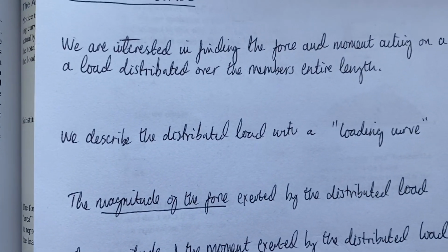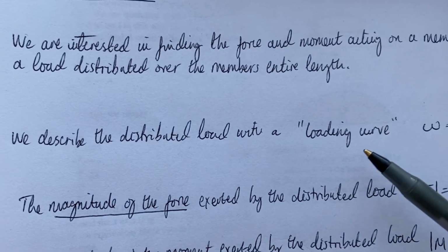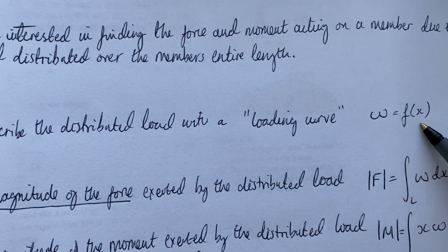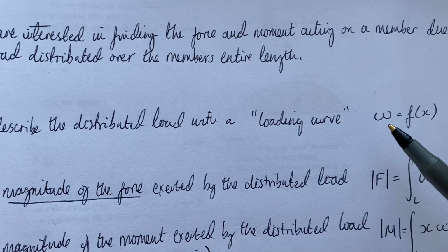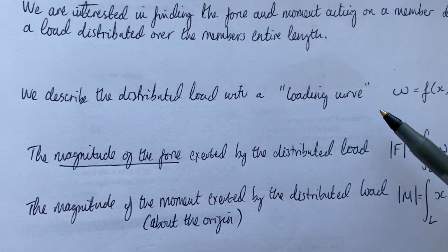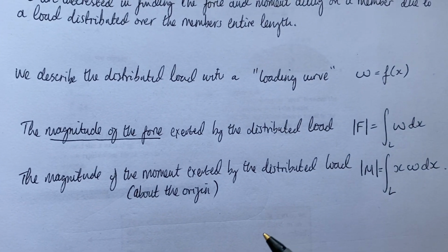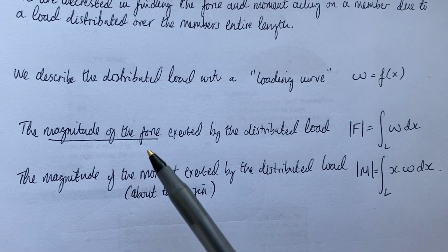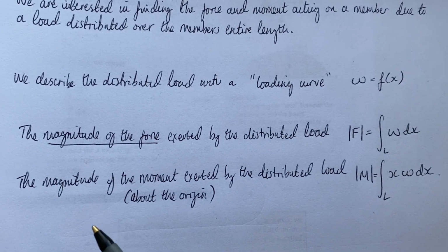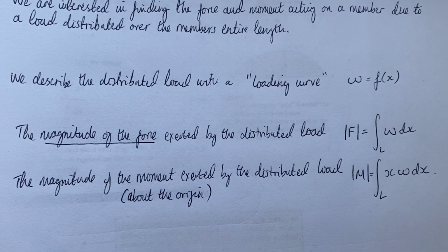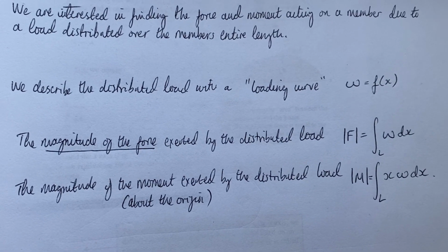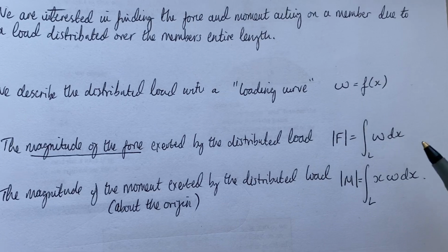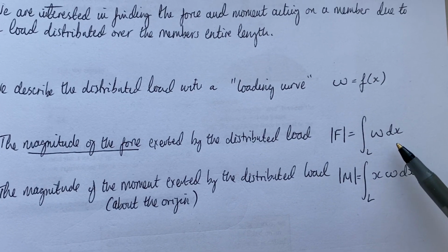So we describe the distributed load by this expression, which is a function of x, and this is called the loading curve, right? And then we can use that loading curve to find the magnitude of the force and the magnitude of the moment acting on the member as a result of the distributed load by doing these integrations, right?